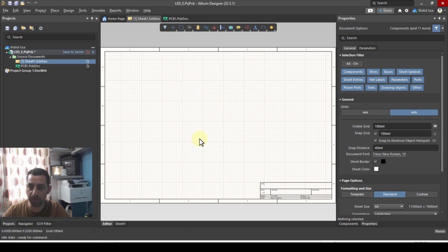in Altium, I think we will face trouble if we already installed a different version of Altium, or we have moved this project to a different machine with different Altium. I think if the components are not really similar by name and by footprint, we will face a big problem, and that will be very frustrating for you. So what is the best practice for this?